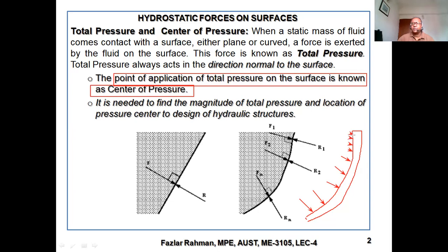At the top surface, it will be 0. Now, how will this resultant be balanced? By the strength of the wall. So your reaction force will work along this direction. That means the wall will resist all the force. Now, the resultant of this force might work through a point, say this point. The location of this point is called the center of pressure.